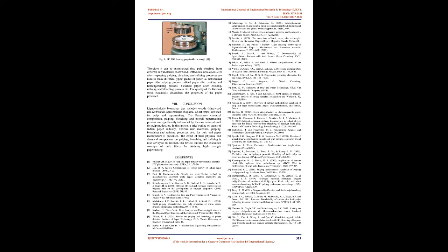Removal of residual lignin during bleaching is regarded as a continuation of pulping process, but it is done in a gentler, less destructive way, hence it is carried out in different stages 30, 31, 32, 33. Due to global trends and environmental pressure for cleaner bleaching processes, ECF, elemental chlorine-free, and TCF, total chlorine-free, are being used more often to reduce the production of chlorinated organic compounds during pulp manufacturing 34, 35, 36.